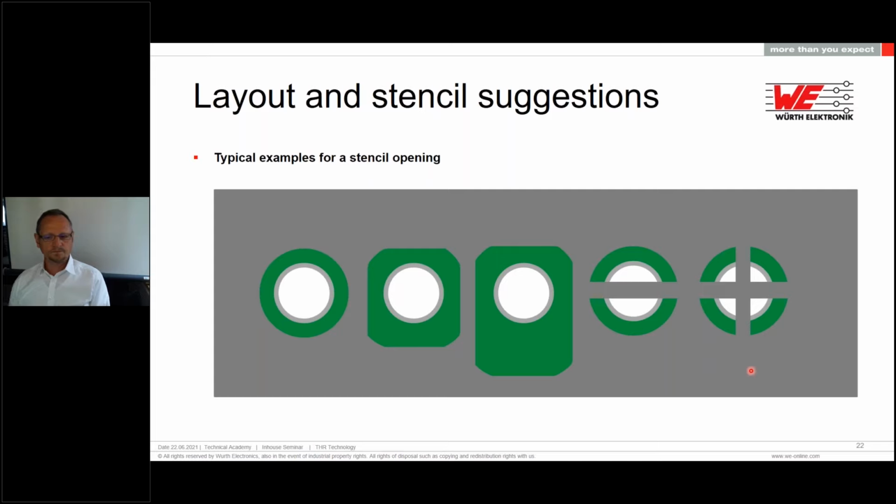So now that we know the amount of the solder paste, how can we get this onto the PCB? Maybe the volume is higher than we expect, and it's more than we use. Of course, for the THT, we don't need this calculation, because on THT, the solder comes from underneath, from the wave. So now we have to apply it up front here, like for SMD components.